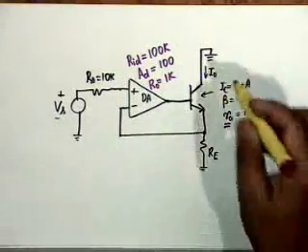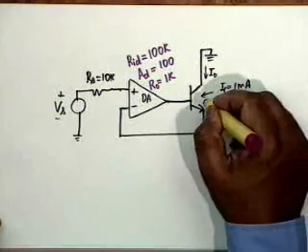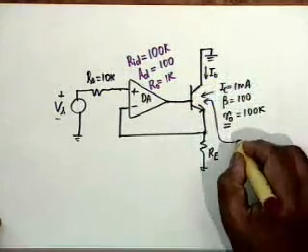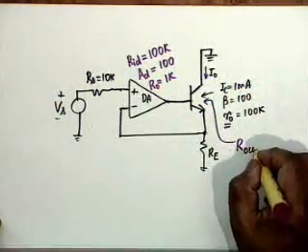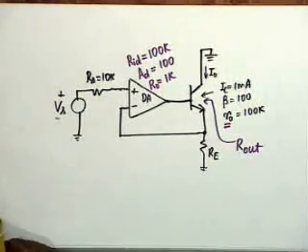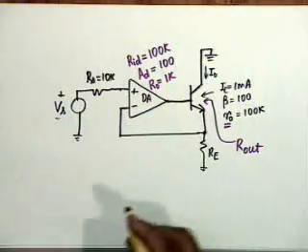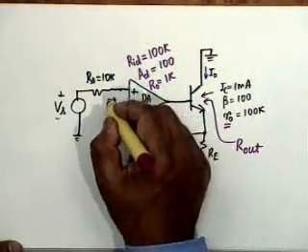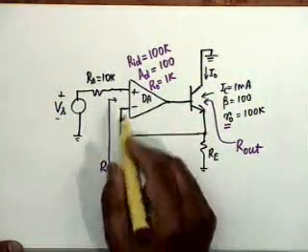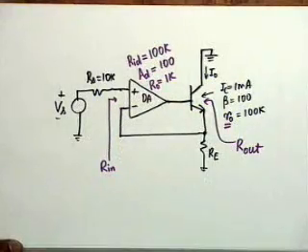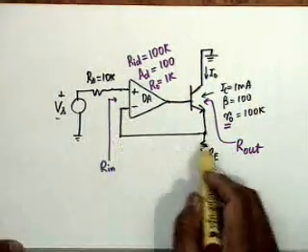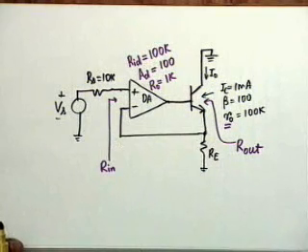So I must change my terminology now. What we have to find out is R, we will call this Rout. I would not use this symbol capital R0. Output resistance. Then we have to find the input resistance, that is looking from here, Rin. Obviously, this will not be RID anymore because there is feedback.